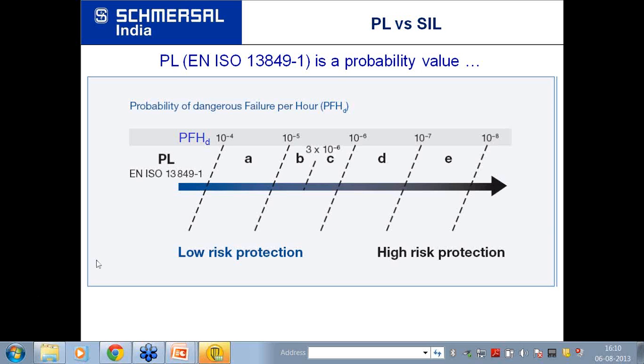Mr. Mahesh has asked, is there any alternative if PLC fails? Alternative is you can hardwire. At least what can be done is you can have one channel going through the PLC and the second channel going directly to the drive. So in case the PLC fails, at least the other channel which is going directly will act and stop the machine or avoid the accident.